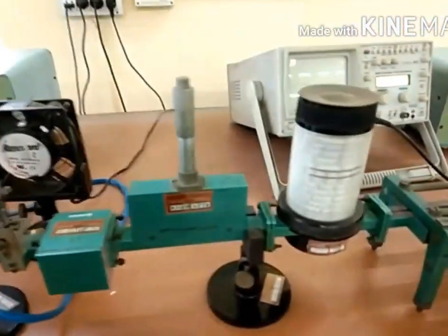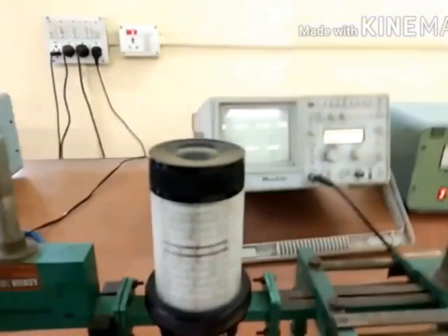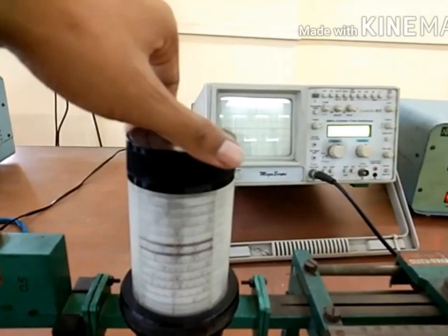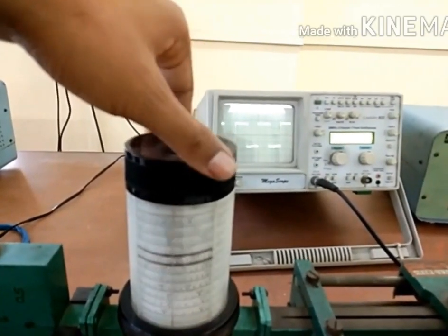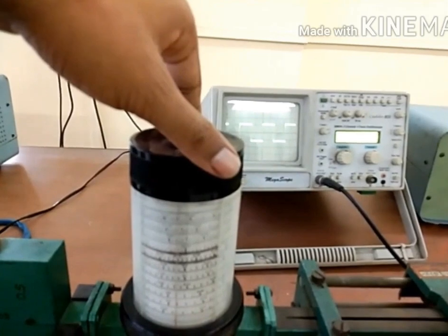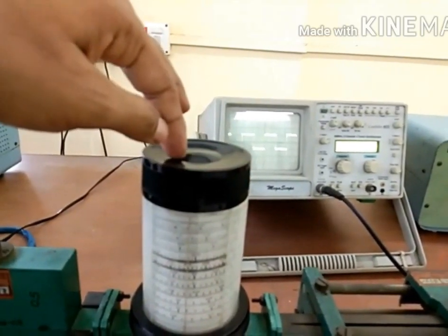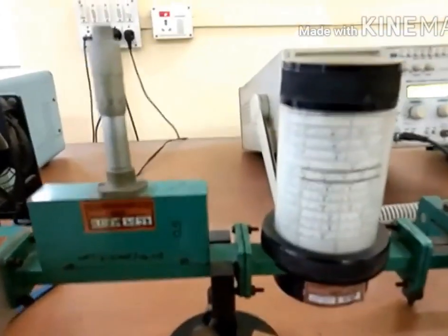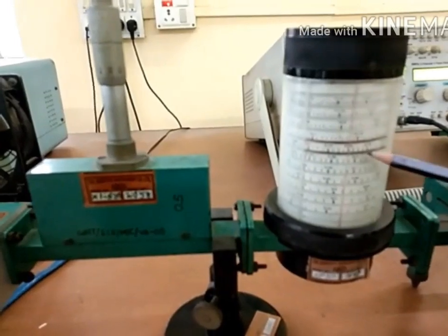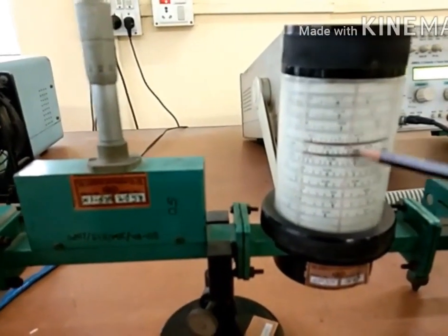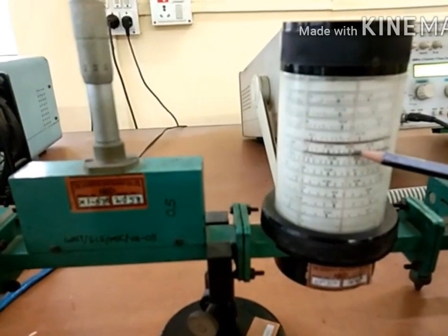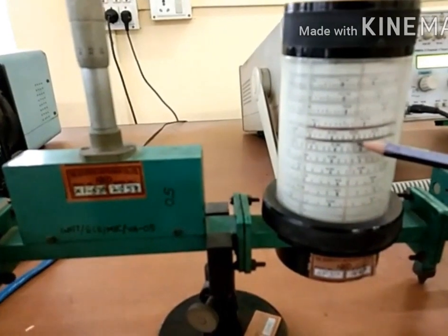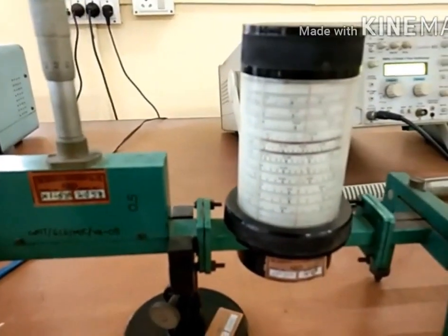Then for the frequency, rotate the frequency meter. When the output signal clips, stop rotating. The value is where the 2 copper foils are and 1 red line meets this point. This is your resonant frequency, that is 9.74 gigahertz.